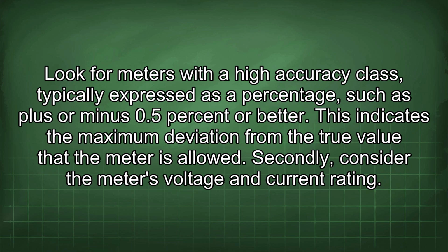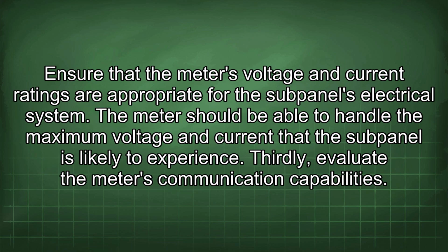Secondly, consider the meter's voltage and current rating. Ensure that the meter's voltage and current ratings are appropriate for the subpanel's electrical system. The meter should be able to handle the maximum voltage and current that the subpanel is likely to experience.